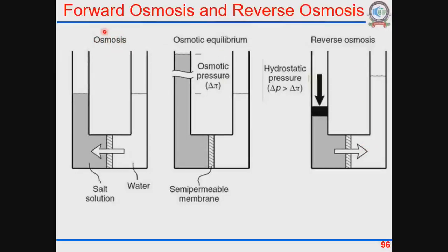So this is called osmosis, or very commonly, just because this is reverse osmosis, this normal osmosis is called forward osmosis, as if this is some different osmosis. But just because this is called reverse osmosis, we give the name forward osmosis here. And at pressure between these, water will still try to go through, but of course at a lesser rate, because I am applying pressure here less than the osmotic pressure. That's called pressure retarded forward osmosis. So we are not going to go into those details right now. We are only going to look at reverse osmosis, only key aspects of reverse osmosis.